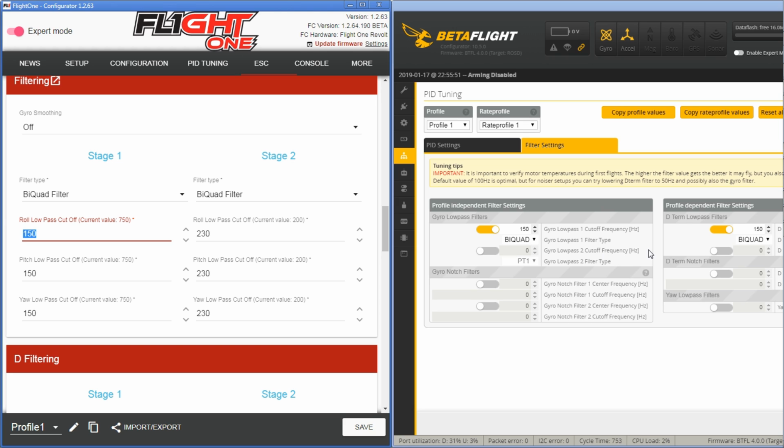I really do wish I could just give you magic settings that just make your filtering world come together. But it's so variable. Honestly, the only way that filtering will be one click and done is if it has to be completely dynamic. And I know Betaflight's working towards that. There's going to be RPM filters coming out that reads the telemetry from your ESCs, like the 32-bit ESCs. There's a couple catches though. First, you have to have 32-bit ESCs. So if you have BLHeli, sorry. So you'll still have the classic or the current Betaflight dynamic notch. This RPM thing will be an option.